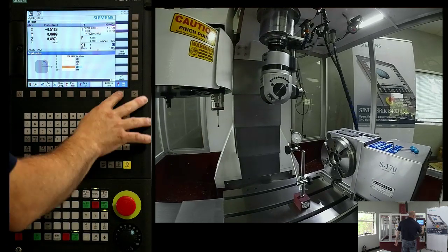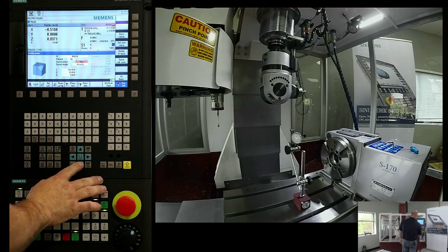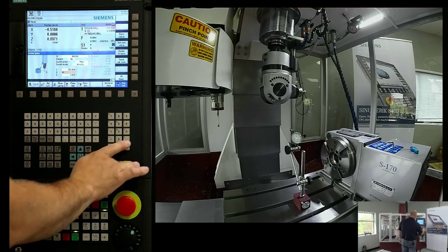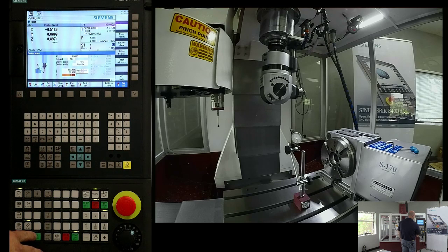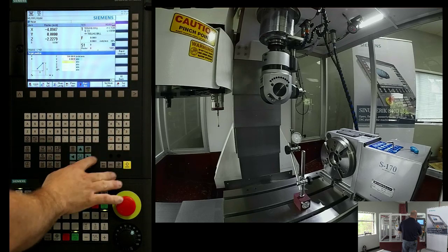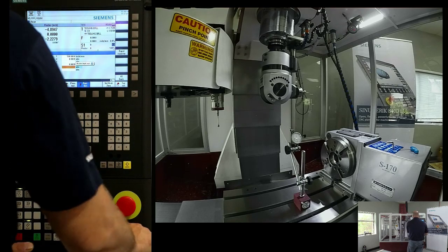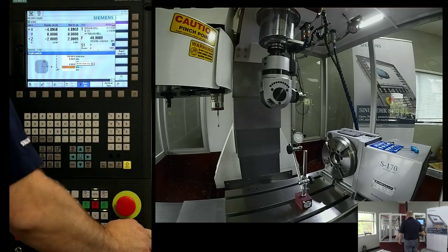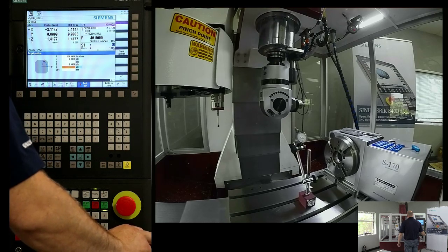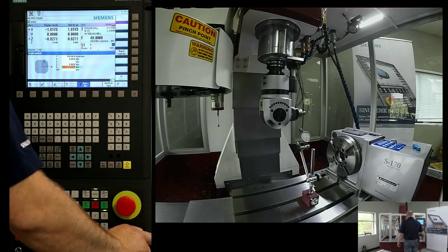Now, remember, I need to reactivate the orientation through the swivel cycle, so she'll compensate. If I was on a full 5-axis machine, I could actually do this dynamically and watch the indicator roll right around that sphere. But it's really the exact same process as I'm showing you today. Now I can position, and if you ever want to check any rotary axes on a 5-axis machine, this is a quick, nice, simple, down and dirty method. You should always be able to track that sphere.